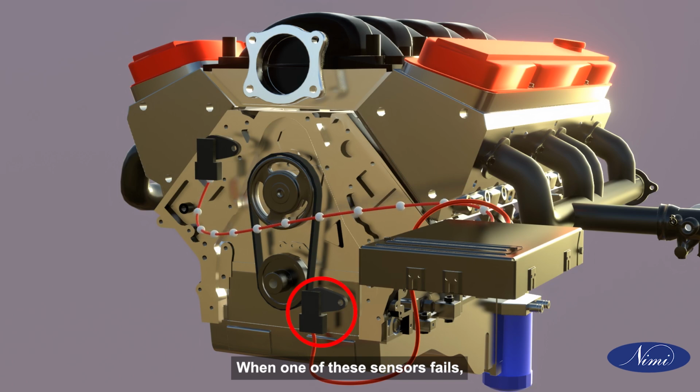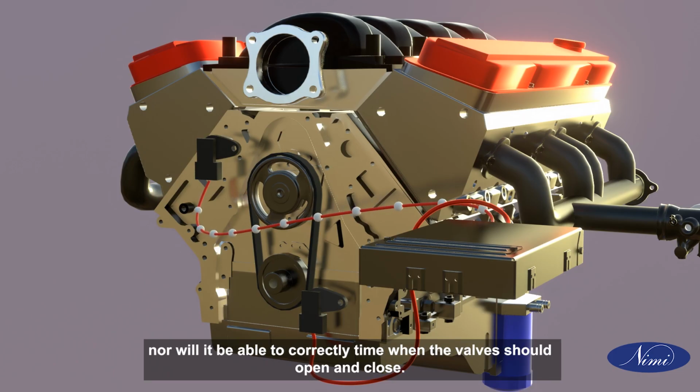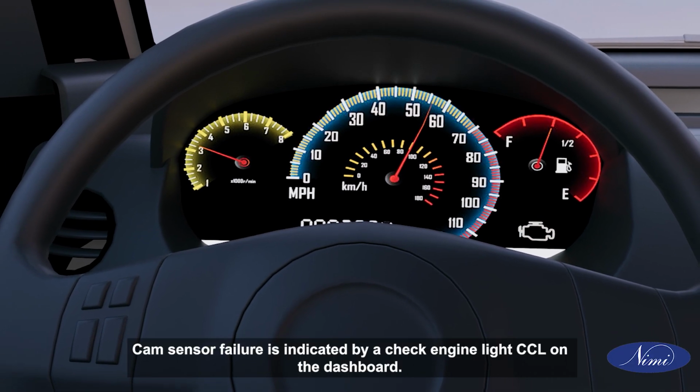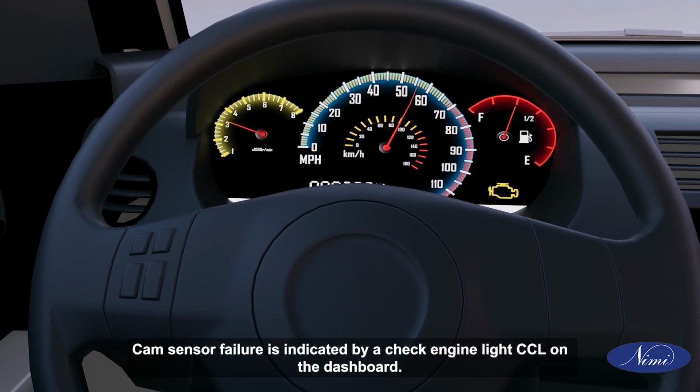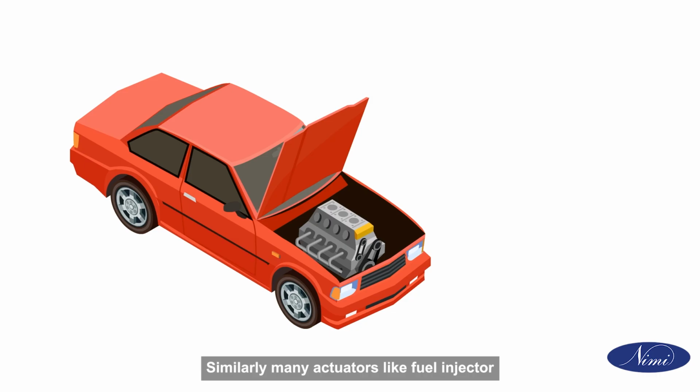When one of these sensors fails, the engine will not start because it cannot determine how much fuel to add, nor will it be able to correctly time when the valves should open and close. Cam sensor failure is indicated by a check engine light (CEL) on the dashboard. Like that, many sensors are used in engines.